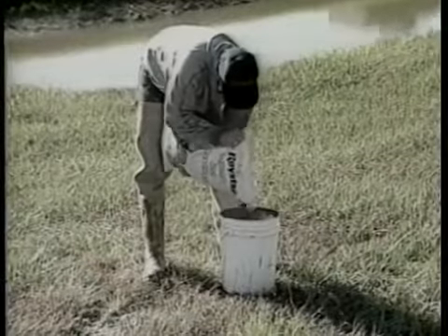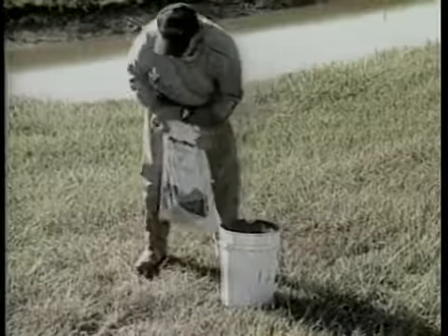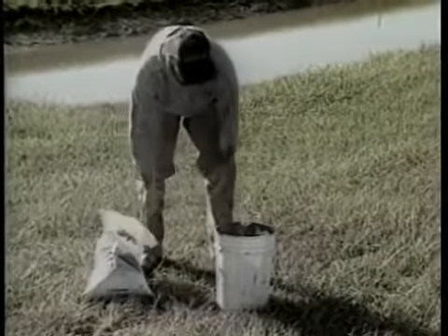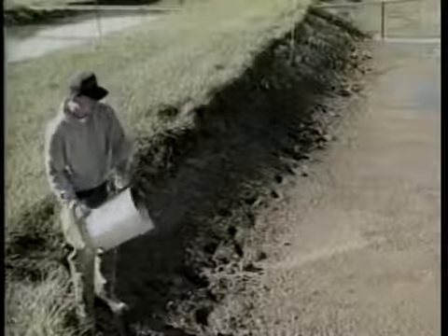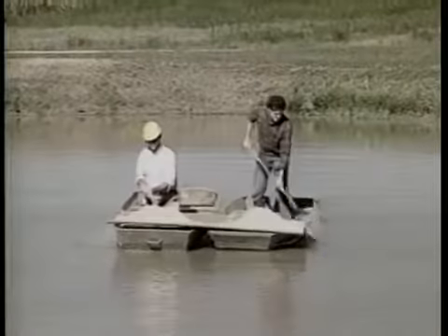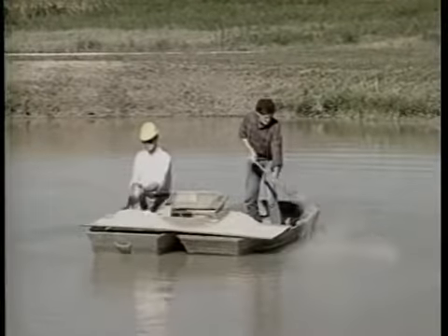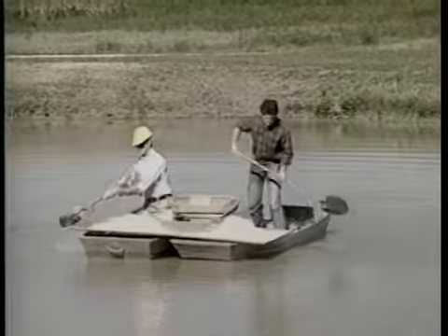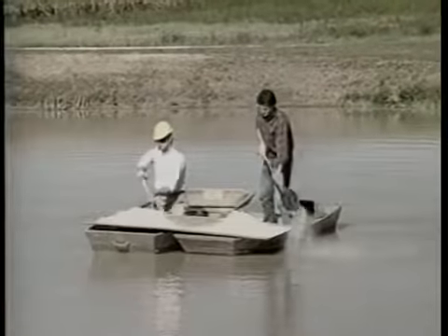If the pond has not yet been filled, the gypsum may be broadcasted over the bottom of the dry pond. Subsequent disking will ensure even distribution and allow the gypsum to react with the pond mud once filled. However, most applications will be in ponds which are full. In this case, gypsum may be placed on a plywood platform on a boat. While navigating the boat throughout the pond, gypsum is evenly distributed.